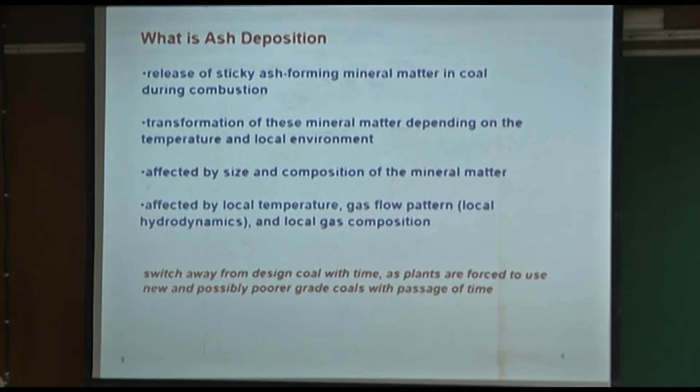Sometimes in the vicinity of the particle, when the carbon in the particle has eaten away all the incoming oxygen, you essentially have a reducing environment, because you have steam in its vicinity. So there, the ash deposition problem can become more aggravated.